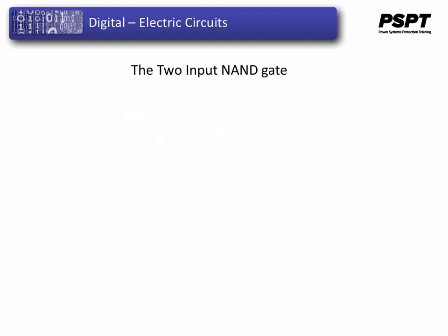A variation on the idea of an AND gate is called a NAND gate. The word NAND is a verbal contraction of the words not and and. Essentially, a NAND gate behaves the same as an AND gate with a NOT or an inverter gate connected to the output terminal. To symbolize this output signal inversion, the NAND gate symbol has a bubble on the output, which differentiates it from a simple AND gate.